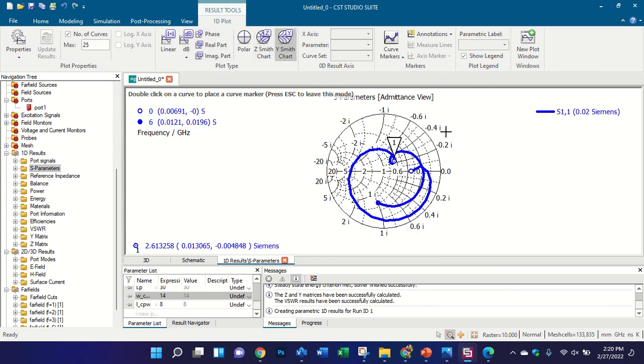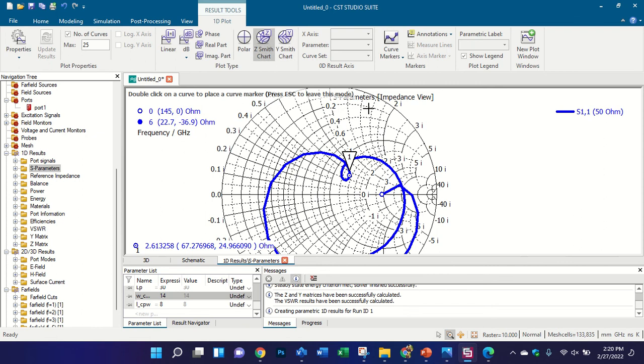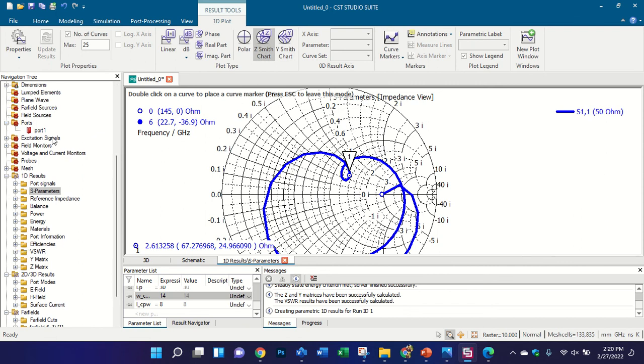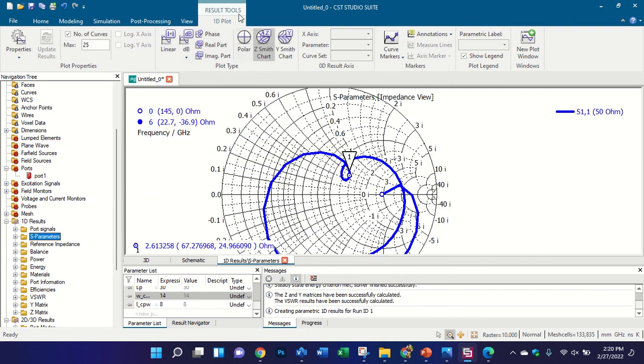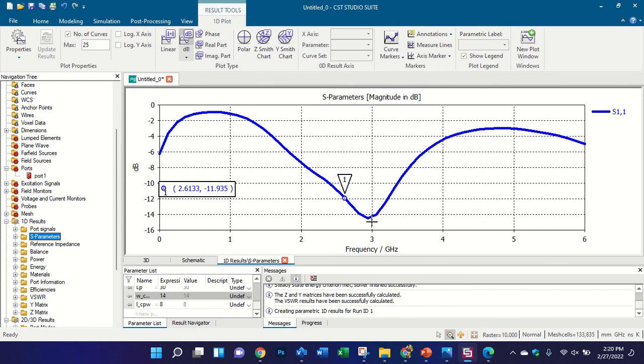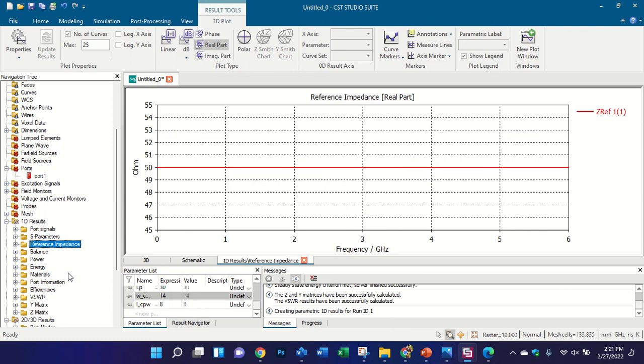Or in the case of voice, you adjusted the impedance, perhaps 50 ohm. Yes, that is at the desired frequency band. At the moment you can see our design is not working properly at 2.6 gigahertz. So if it is not working at the desired frequency band, then it means... let me check here, it is 50 ohm, yes, but you have to set this impedance at the desired frequency band.